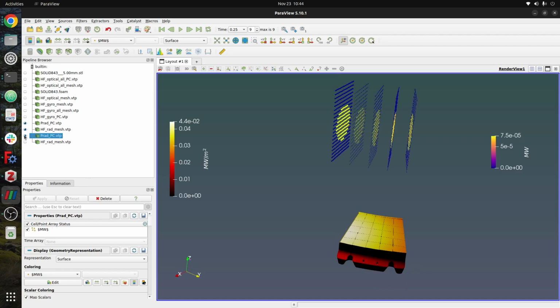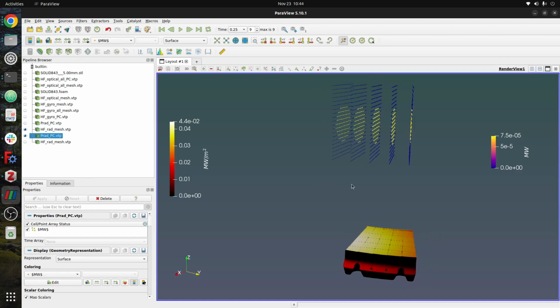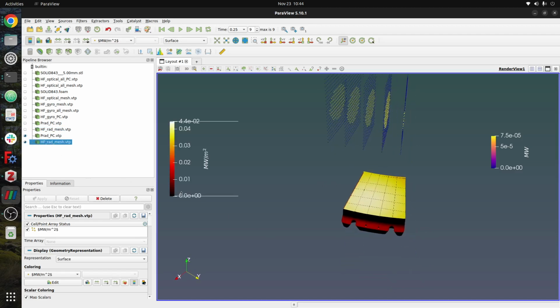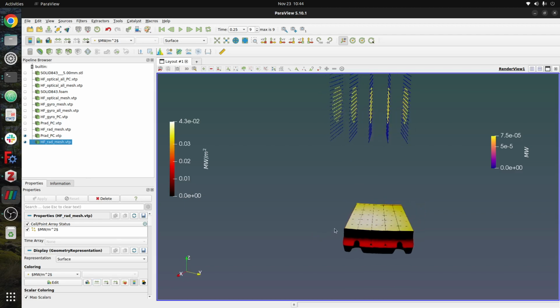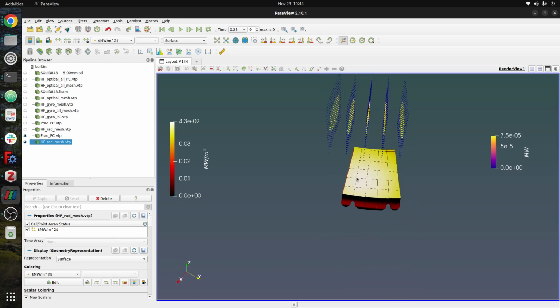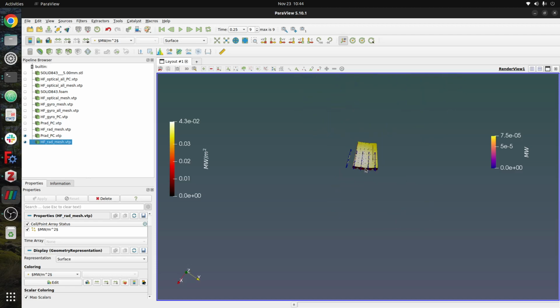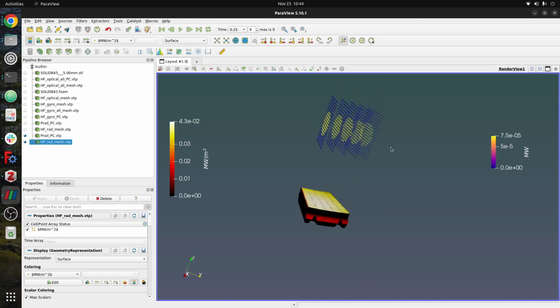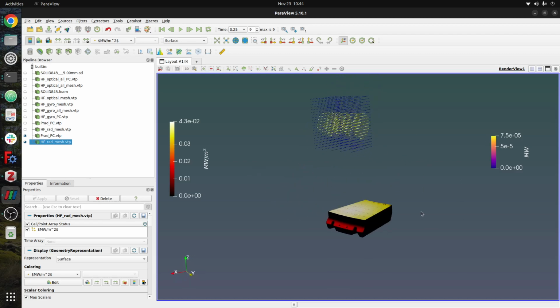And then if we look at our 5 different slices and we look at the profile for that, so let me turn off that one, it's much more uniform. It'll still be a little bit discrete. You can see that it's sort of favoring over here. It's a little bit whiter than it is over here, and that's because this doesn't cover this PFC fully. See that? So in the limit, as you increase the width of your toroidal angle and you increase the number of toroidal slices that we're using here, this profile will converge to the real heat flux profile. So it's up to the user to go through and figure that out. But yeah, that's basically how you run it.